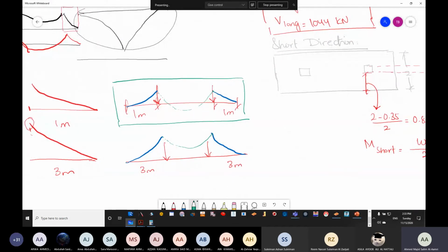But anyhow, if you can see here, we draw the bending moment, and according to the bending moment, we do the reinforcement. Now, in scenario number one, since there is a top bending moment, we provide reinforcement. On the other side, the same thing. Since there is a top bending moment, we provide reinforcement. Now, when we come to the bottom, we provide the reinforcement here as well. In reality, when it comes to the foundation, we extend the reinforcement from the beginning till the end. So we have the reinforcement in both directions due to the bending moment diagram.